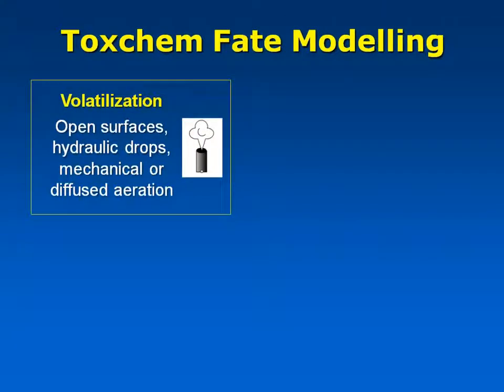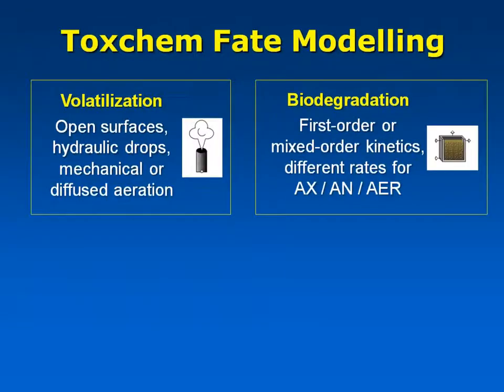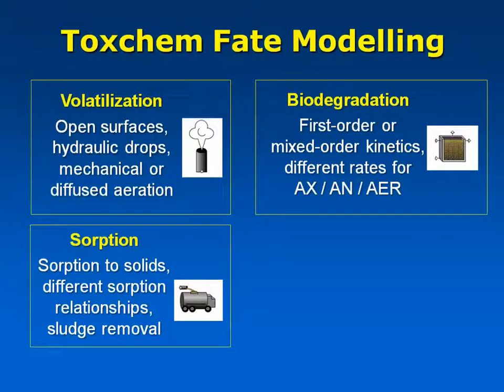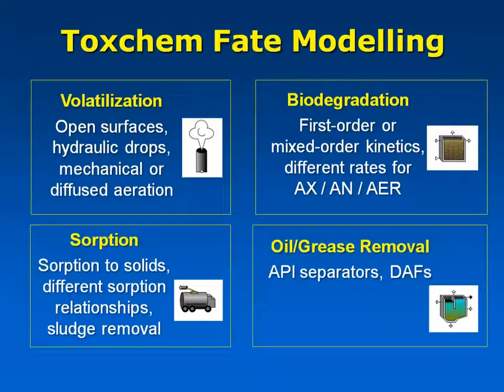So Toxchem basically takes 4 approaches to this. We model the volatilization from open surfaces and hydraulic drops and so forth. We do the biodegradation. We have a number of different ways of doing that, and we also model the sorption. There's a couple of different sorption equations that can be used, whatever's most appropriate for each system. And oil and grease removal.